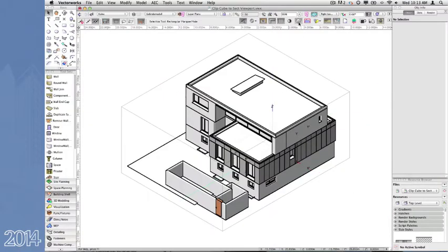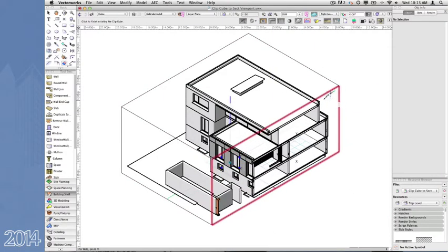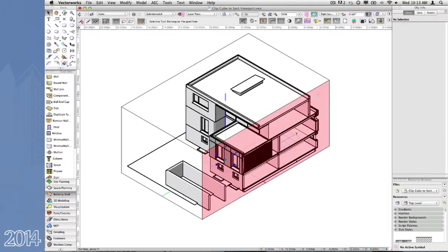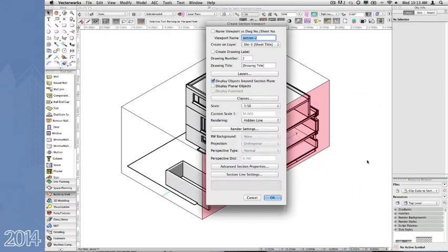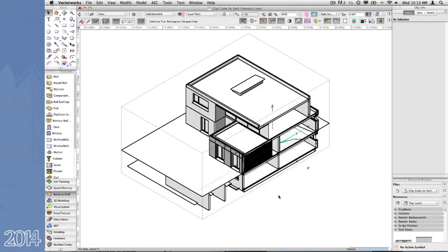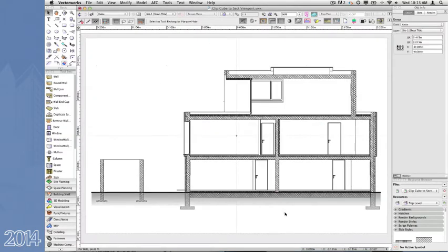Simply generate a ClipCube view as before by setting the cube face as desired. Then right-click on the cube face. You'll notice a new option to create a section viewport. You'll have all the same properties and annotation capabilities from this section viewport as with any other section viewport on a sheet layer. For example, we created this ground line to embellish the look of the section.